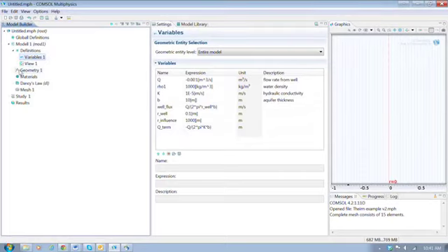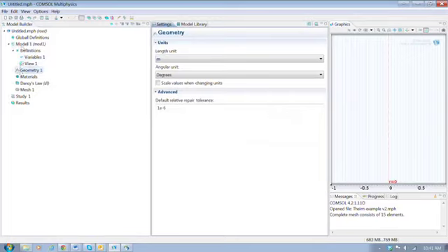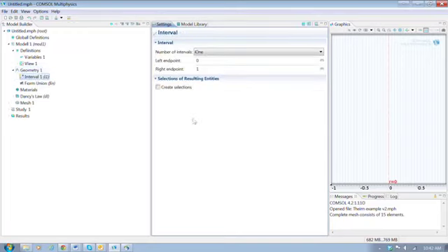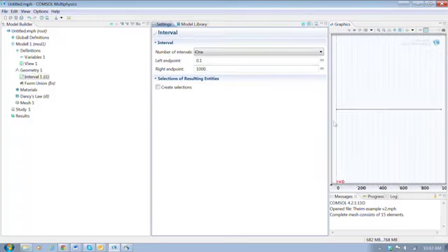Now, the next step will be to go here in the geometry. We'll just really progress from top to bottom, and the geometry that we'll use for this problem is just a line. This is just a 1D problem, so it's very simple geometry. And I just right-clicked, and I'm going to put in this interval. And so the line will be from 0.1 to 1,000. And if I click that button, I build it, and there's the line.